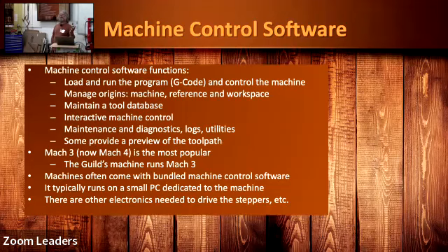One of the mistakes you might make is, oh, I told the design software the origin was in the middle of my piece of material, but I didn't set the machine up that way. I told it that it's actually the corner of the material. Oops, that's a problem. It doesn't know if it's routing error or your part. No, it doesn't, and it doesn't really care. Just does what you told it.